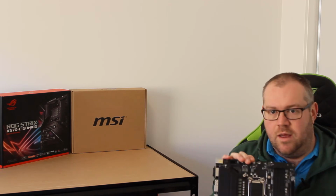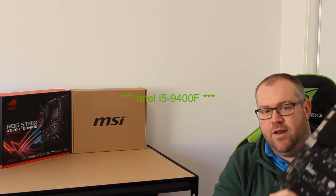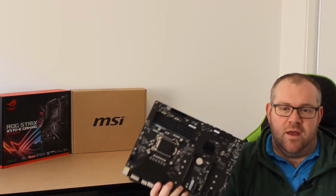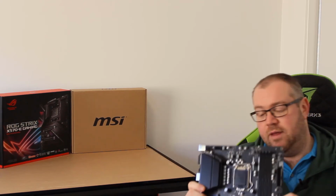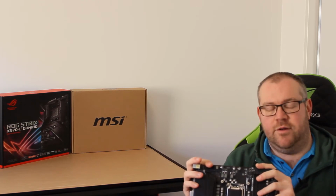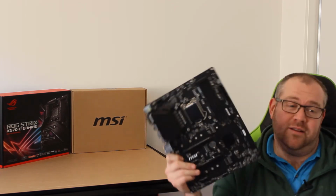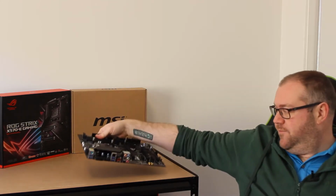Now, with this one here, I put in this board an Intel i5 9400F processor, which meant when I chose that processor, I had to choose a board that had the right socket configuration. This CPU had a configuration known as LGA 1151. And that's why I've chosen this board, which is an MSI Z390 board. It has the LGA 1151 socket in it.